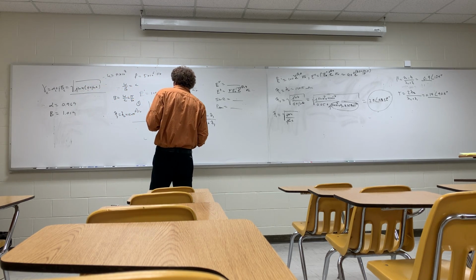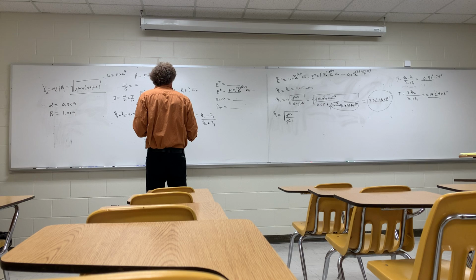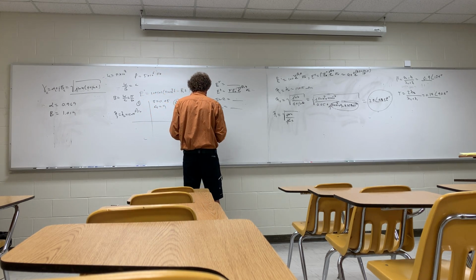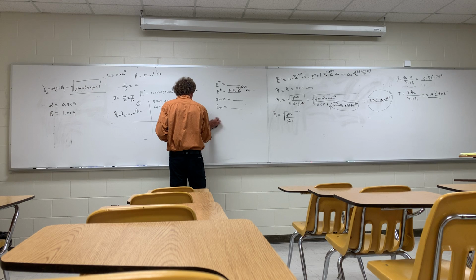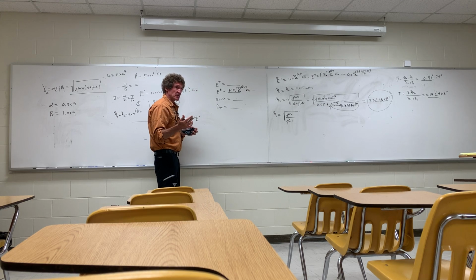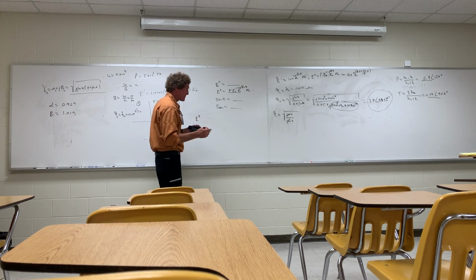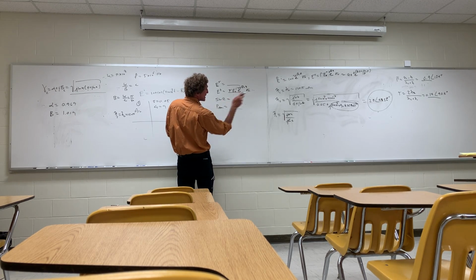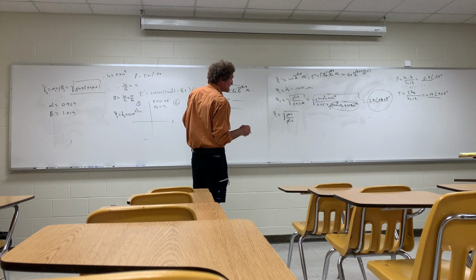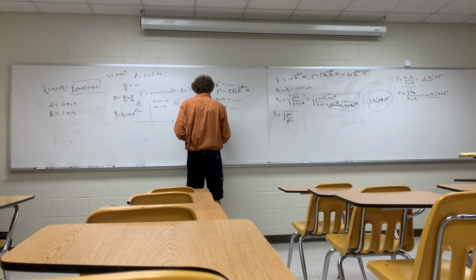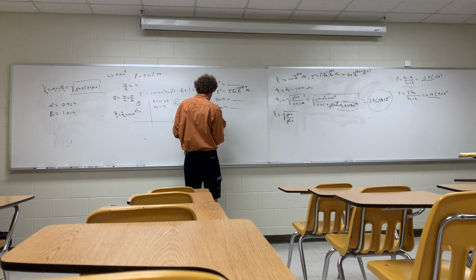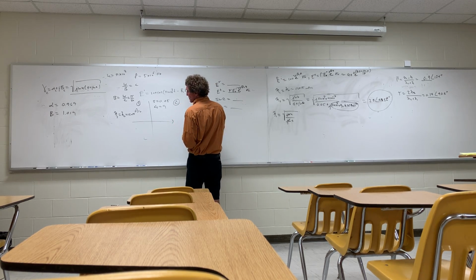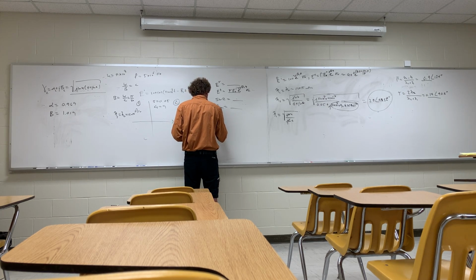So now, if you have that and you want the actual transmitted field right here, and I'll put the formula right here. Now I can say that E transmitted in the phasor domain. Time domain's easy to get, but once you get phasor, is gonna be the transmission coefficient, which is 0.14, times the incident field, so it's 14. All right? Then you're gonna put the e to the minus alpha z, which is 0.969 z.